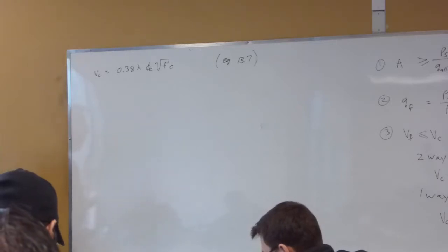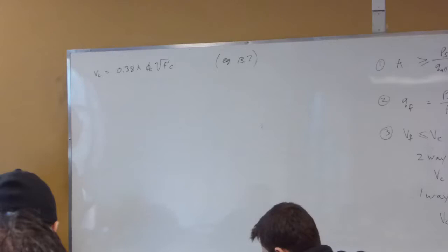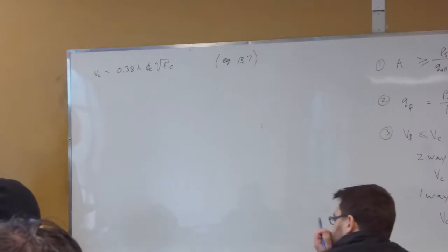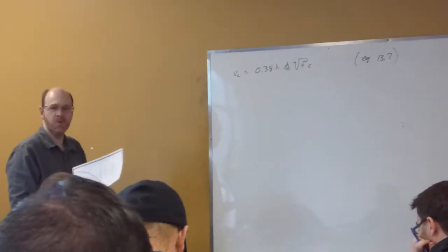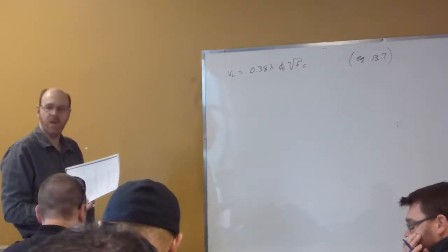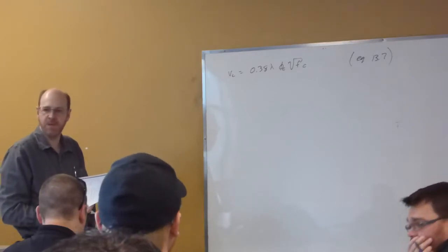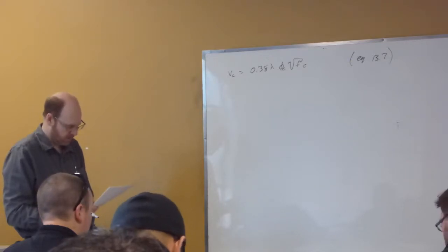So there are three equations that are listed in the code, and it is commonly assumed that this is the one that governs. If I've got a standard configuration, square column, square footing, bending is exactly the same in both directions, nothing's out of the ordinary, then usually this equation is in fact the governing one. So we're not going to check the other two equations for this example, but if you... Pardon me? You sure it's 13.7?